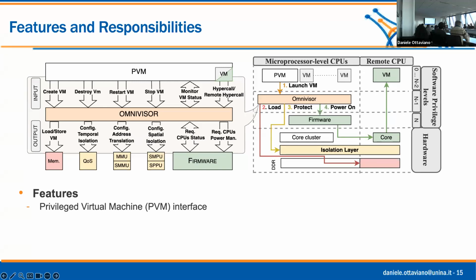Right, but in a traditional system, in order to do that you have to set the page tables for them, and you're controlling that, which is actually on the path, and there is a virtualization overhead to all that. Here, there's none of that. Yeah, there is one clock cycle of overhead for the MPU. Okay, so low overhead. But there is a translation happening from guest physical to host physical. No, for these ones, no. They don't have an MMU, they don't go through the SMMU, they go straight to memory.